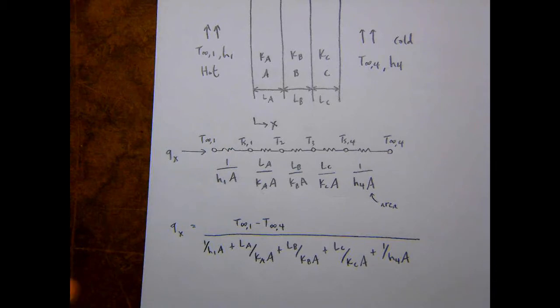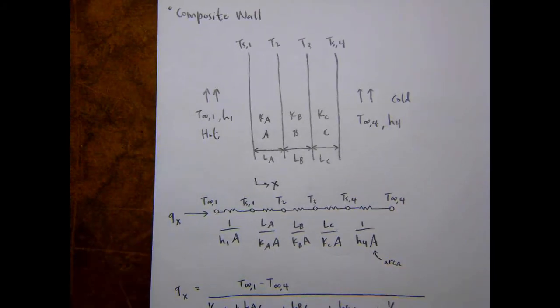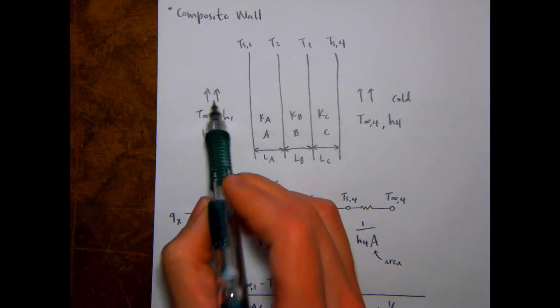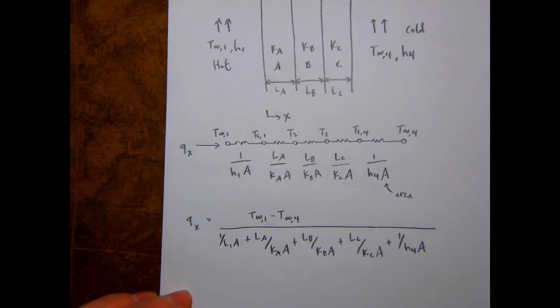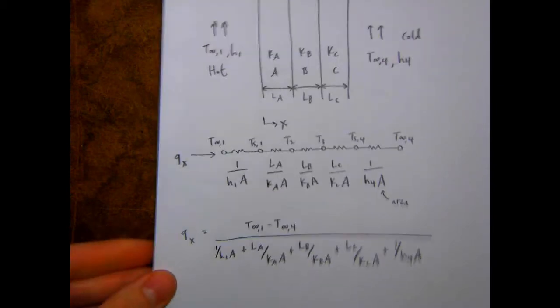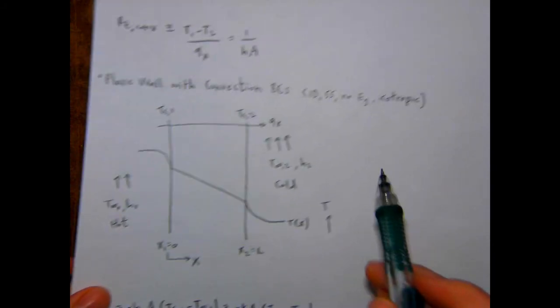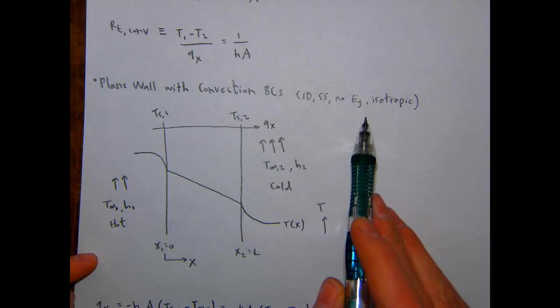But if you just think about a setup where x is in this direction, then the equation is just going to come down to this temperature minus this temperature with no negative there. So the heat transfer through a wall is always going to be equal in and out? Is that universal? With these assumptions, yes. So that's why I always try to emphasize.